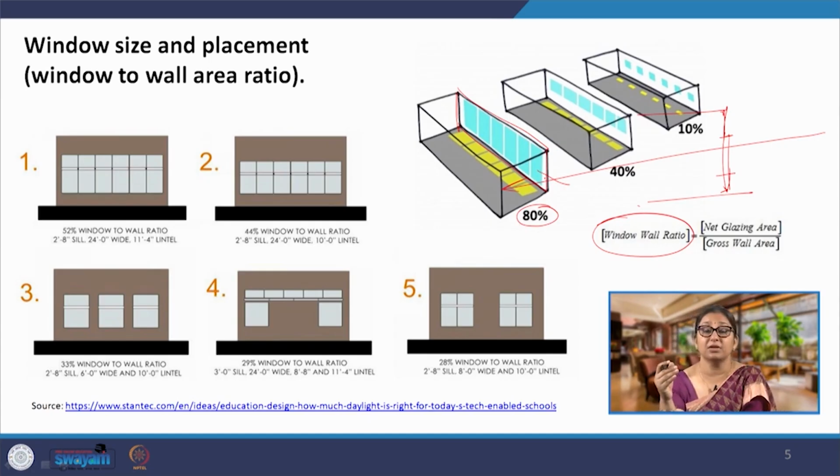So, what we would prefer while designing a building is that the studios have a north wall, a north facade, and it is glazed largely. So, a lot of light is coming, and then we also have to see to which side the class should face. A large number of people are right-handed. There are fewer who are left-handed. So, the majority of us will be working with our right hand like this. So, we would want the light to be coming from the left side.